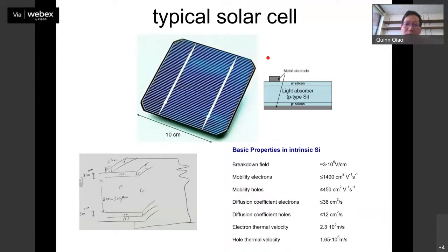You see, it's a silicon solar cell because it looks blue, and there's a lot of wire here, a lot of wire here. See all these wires? This is the contact. You can just call these the small fingers. So the small fingers collect all the charge. Then here, there are big wires. Typically, you call the small wires the contact, and the thick wire you call the bus, right? Because a bus can hold more people. The same thing, this big wire can hold more electrons, so it moves electrons quickly.